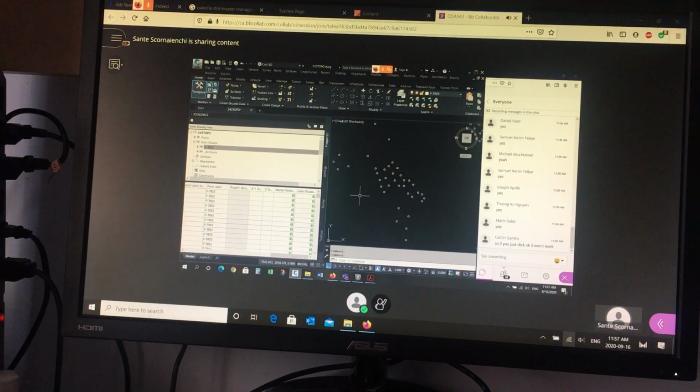So imagine you go to work. Your description keys are all programmed. Your layers are all created. The color and line type of those layers is all defined, which we haven't even talked about yet. Your point groups are all ready with all the different styles. Your styles have all been created. When you import the points, you'll see everything on the correct layer, the correct color, with the correct style, with the correct label style. That's a lot of drafting taken care of, so it's pretty quick.